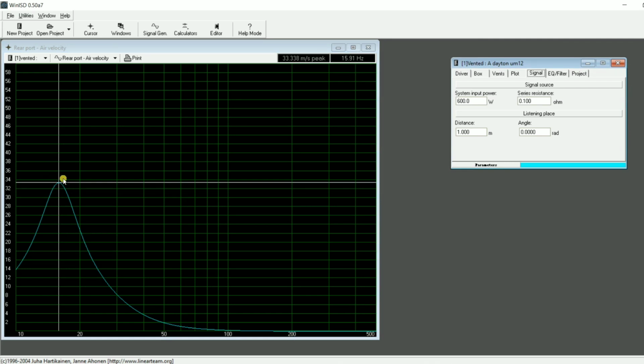Now, rear ported, you can go a little bit higher than that. I mean, front ported, you can go higher than that too, really. I've gone up to 50 and I still don't have any problems, but it's because I put a filter on it. So if I put a filter on this one at say 16 or 17 hertz, I'm going to start sloping off here. I'm never going to get quite to that peak air velocity. I'm going to start cutting it short before it gets there. But it's just a good rule of thumb: 30-ish, low 30s is a good target to not exceed.